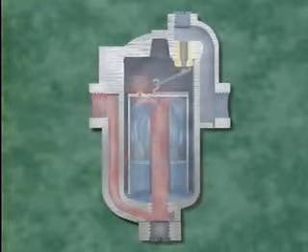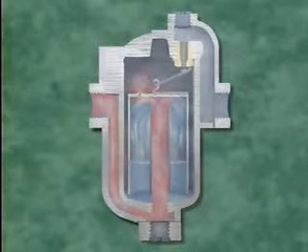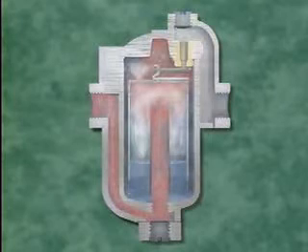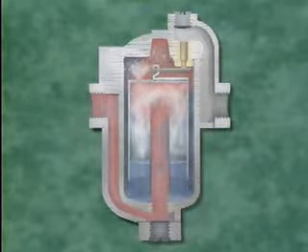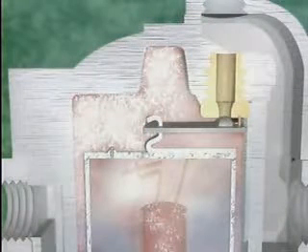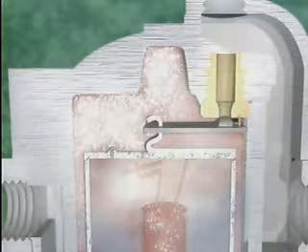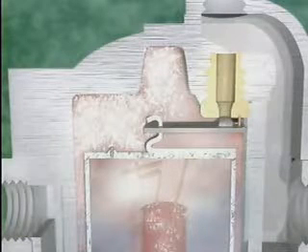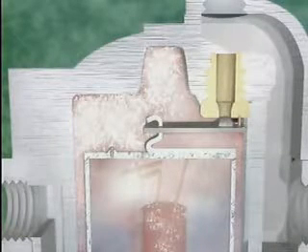When steam enters and accumulates to fill about 2/3 of the bucket, the bucket floats and the trap valve closes, so no more condensate discharges. While the valve remains closed, air and non-condensable gases, which are less dense than the condensate, pass through the bucket's vent and collect in the cap area of the casing.